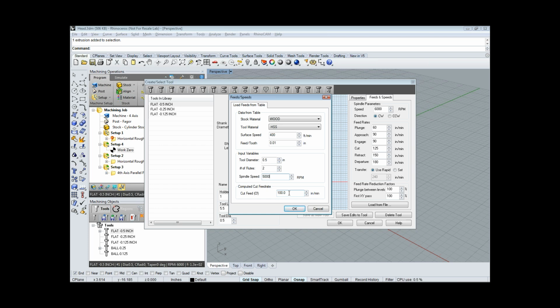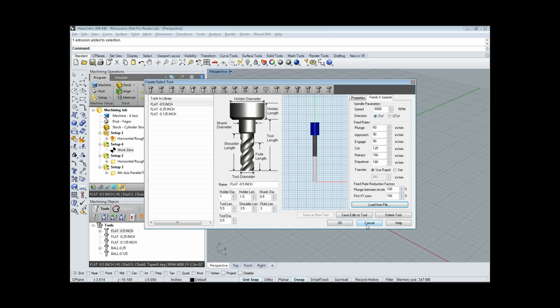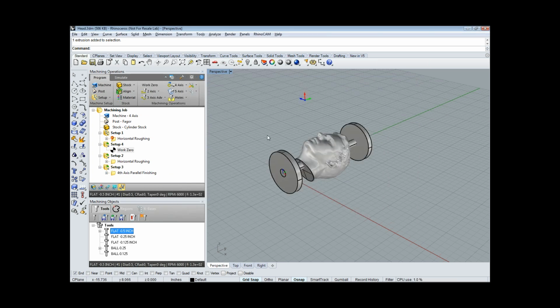All right. So we're going to do 2 more questions, running out of time here. Can the tool wear be programmed? Is there an easy tool wear program tool in the program? Are they referring to a tool wear for cutter compensation? If that is the case, in 2-axis operations, we do have the ability to turn on compensations in profiling, pocketing, and facing, where the tool can be compensated at the controller, and we can output a cutter compensation left or right. It could be a G41 or a G42.